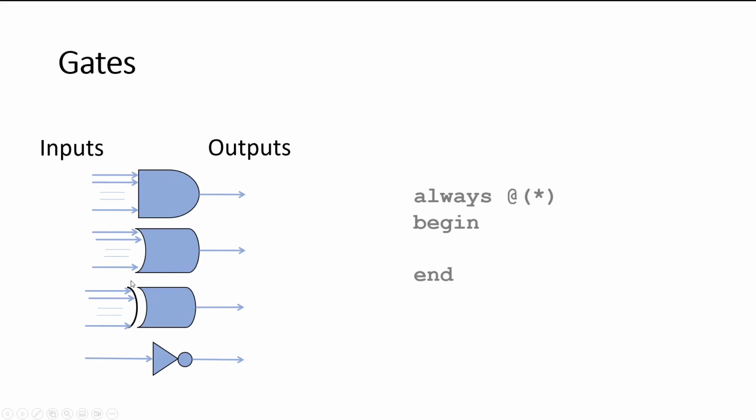An XOR gate is called exclusive OR. It's similar to OR with one difference. If there are two inputs, then it outputs 1 if only one of those inputs is 1. In other words, we have 1 exclusively at one of the inputs. If both of the inputs are 1, it will output 0. For more than 2 inputs, it acts as an odd parity gate. But let's skip that. Google it if you like. We use the caret symbol for the XOR gate, and that's it.